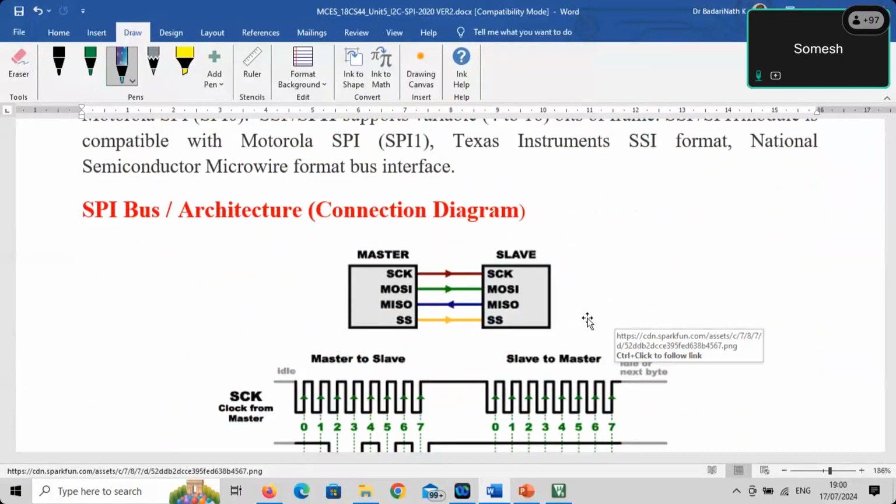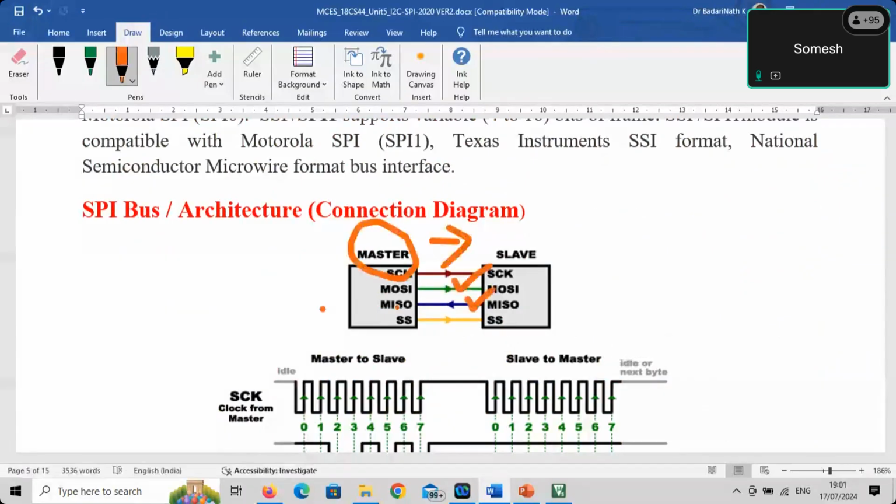So that means that if the master wants to communicate to the slave, it uses one of the lines to send the data, like transmit data in UART. The name of this pin is MOSI, master output slave input. That means data communicated from the master to the slave goes through this pin. Similarly, when the master wants to read data from a slave, one more separate pin is provided, MISO, master input slave output. That means the slave sends the data on this line and the master receives it. So that's why it's called full duplex.